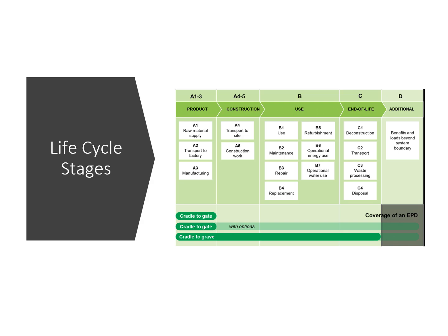As previously stated, an EPD for ready-mix concrete typically has a life cycle assessment of cradle to gate, from raw material extraction to the factory gate before it's transported to the consumer. If we look at cradle to grave, we are looking at a process that encompasses raw material extraction through the product's use and disposal. Cradle to cradle includes reuse or recycling at the end of the product's life.